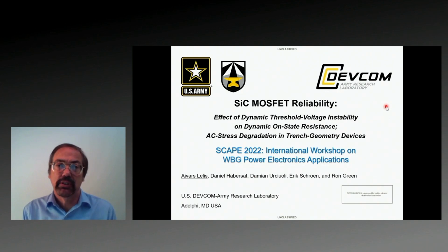The title of my talk is Silicon Carbide MOSFET Reliability, and today I'm going to focus specifically on the threshold voltage instability work that we've been performing at our lab the last 2 years. There are 2 specific aspects of that. One is looking at the effect of dynamic threshold voltage instability on dynamic on-state resistance. And the other aspect is AC stress degradation, specifically that occurs in trench geometry devices.